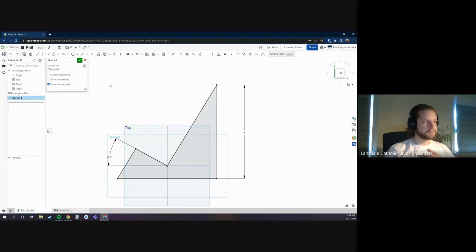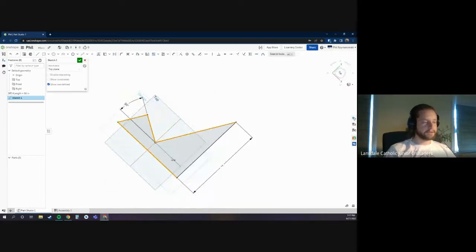And a good example is if I select the whole thing, except for the far right line, with a right select box, I won't select the upper or the lower line. Whereas if I do the same selection from the bottom right or from the top right to the left, I will select all 3 of those lines except for the far right. And again, you can help yourself by rotating your sketch.